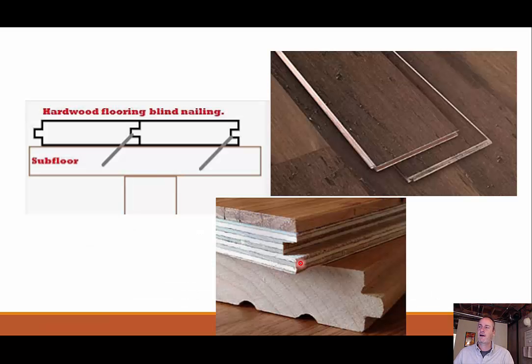So when we talk about attaching our hardwood, it's called blind nailing. I think we talked about blind nailing briefly. Basically what you're doing is you're nailing through the tongue of each piece.